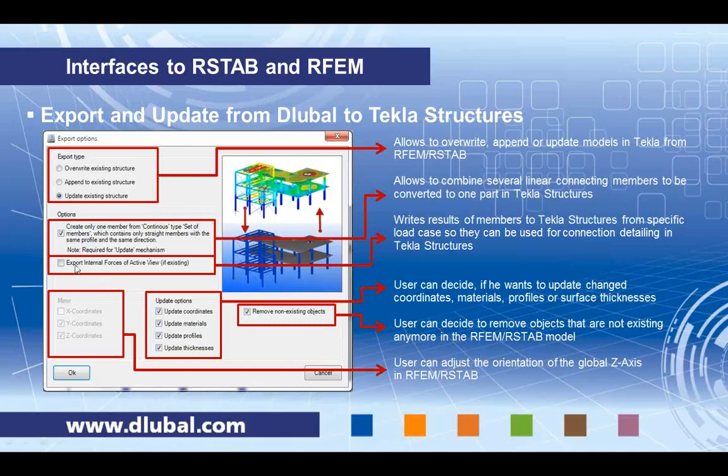I can also update the Tekla model with additional information like internal forces, and these internal forces can then be used inside Tekla structures to have a better idea of what type of connection and which type of bolts and thickness of plates I might have to use. So Tekla inside has the option to display internal forces, and we can fill these fields with the correct values from the calculation.